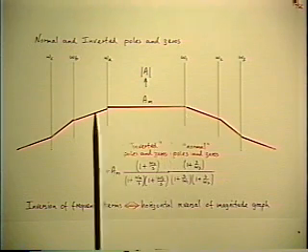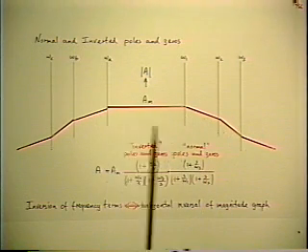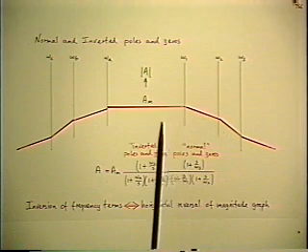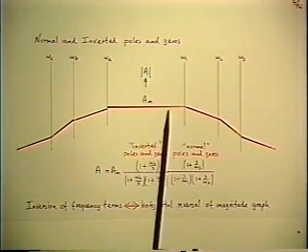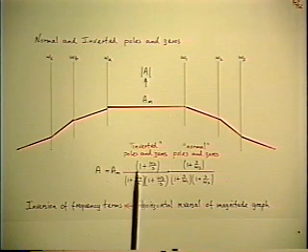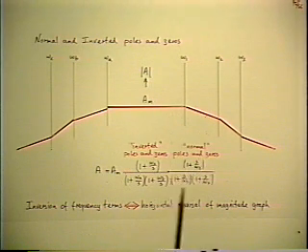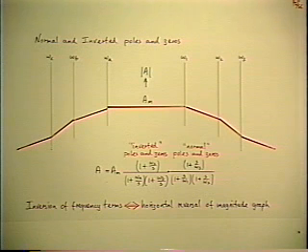So here's a frequency response with one flat gain. Take that as reference by writing it in front. And now when you look down in frequency, you have the inverted poles and zeros. When you look up, you have the normal poles and zeros, and they're all there together.